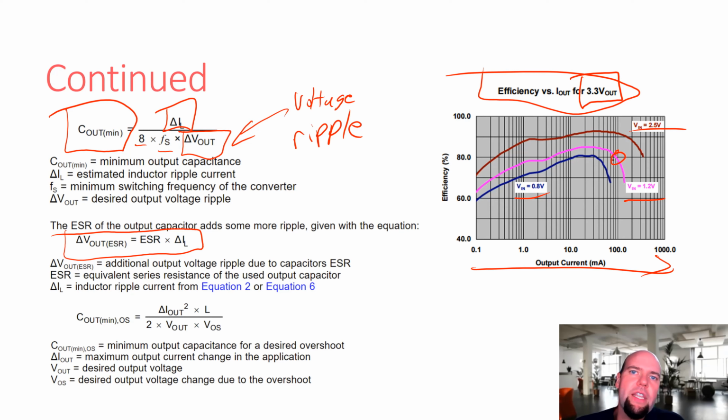And that's usually something that tells you whether or not this is the switching regulator for you. If you're operating out in the weeds over here with your regulator, you might want to upgrade yourself to a slightly bigger, better regulator. You don't want to push it. You notice these curves fall off pretty fast. That's fairly standard for all switching regulators. So you don't want to operate in here. You want to be operating somewhere in this territory here.